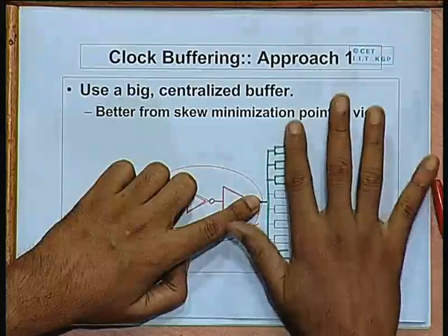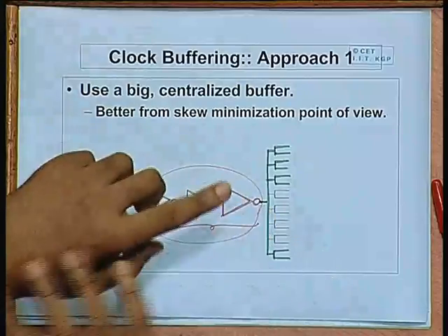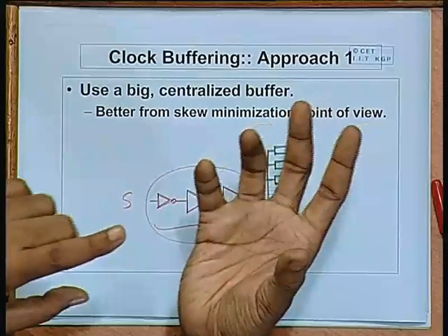So, what's the point in taking three buffers of increasing size, because the current drive for the chips is ultimately being supplied only by the last buffer? No, see, this is a standard method of designing high current driving capability. Suppose you have a requirement to drive a very high capacity load. Ultimately, in terms of a VLSI chip, these are all typically CMOS gates which need to be driven. So, from this point you can look at it as driving a very high capacitive load.